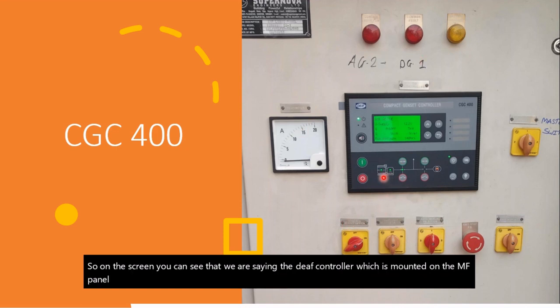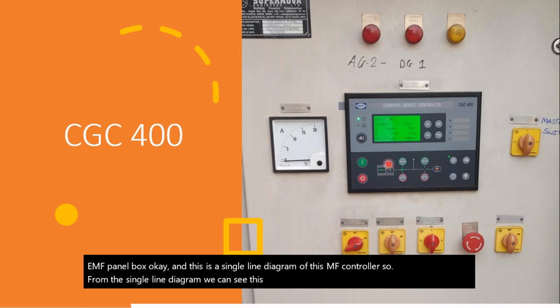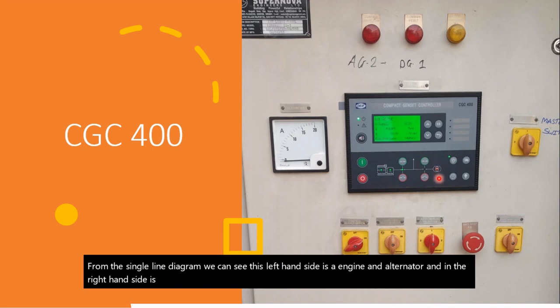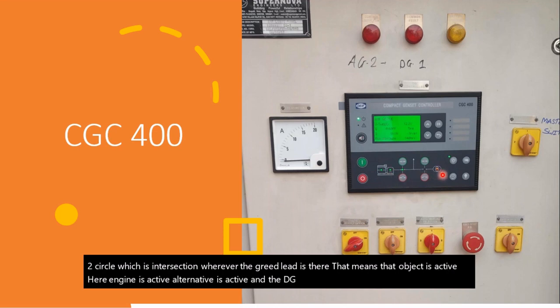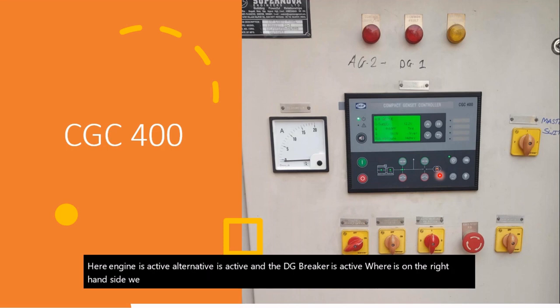And this is a single line diagram of this AMF controller. From the single line diagram we can see the left hand side is the engine and alternator, and the right hand side is the grid part, shown in the two circles at the intersection. Wherever the LED is on, that means that object is active. Here the engine is active, the alternator is active and the DG breaker is active, whereas on the right hand side we see that grid power has failed, so that is why it is a red indication.